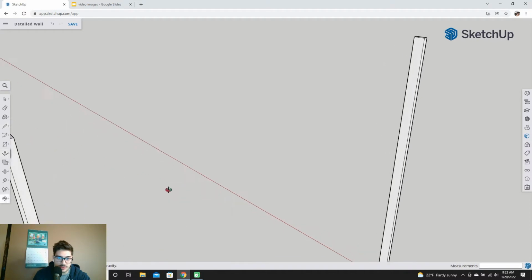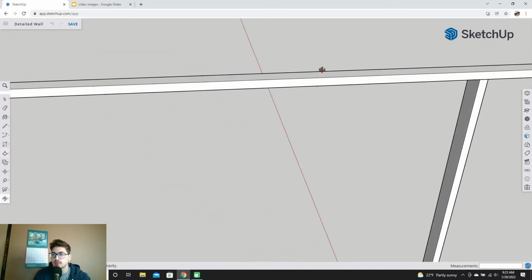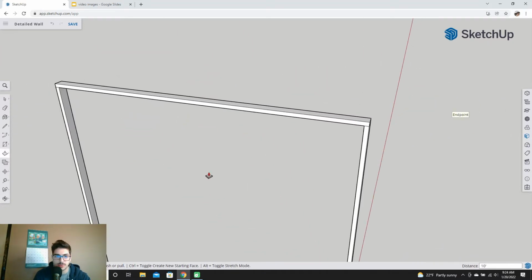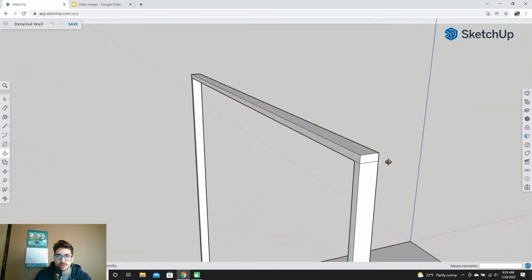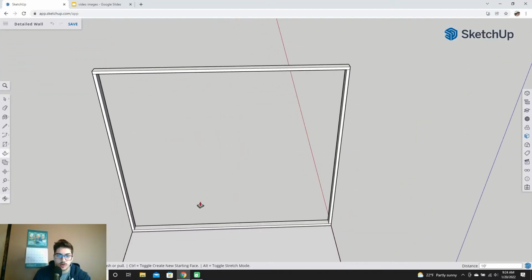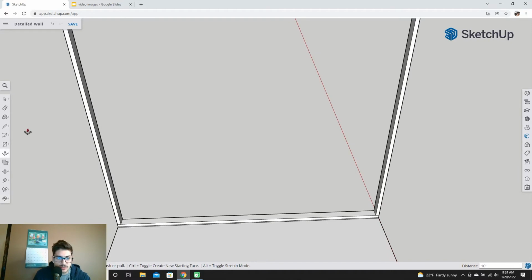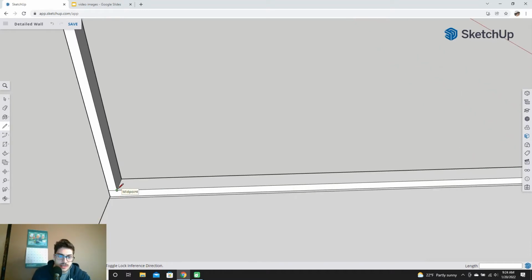And so we'll grab that rectangle just like we have every time so far, and we're going to drag it all the way to this end point, and it'll just snap in place. And so that was probably the fastest stud we've made yet. We check that we don't need to backfill and make sure it looks good. But just zooming out, we have this rectangle of our stud wall already going, and now snapping in the rest is going to be pretty quick. I'll show you how. There's this thing in framing called on center, and all that means is that 16 inches is the most typical that I've seen for interior walls, 16 inches on center for your stud walls.